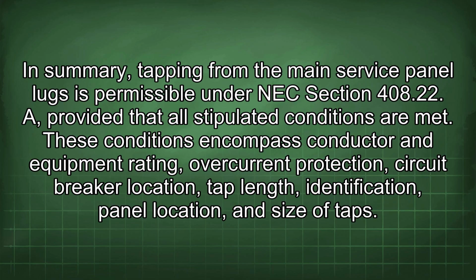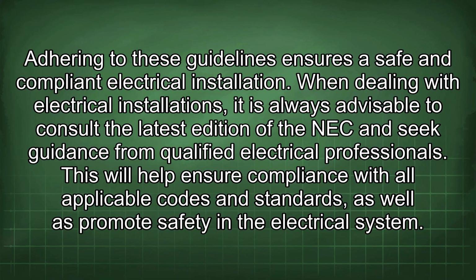In summary, tapping from the main service panel lugs is permissible under NEC Section 408.22, provided that all stipulated conditions are met. These conditions encompass conductor and equipment rating, overcurrent protection, circuit breaker location, tap length, identification, panel location, and size of taps. Adhering to these guidelines ensures a safe and compliant electrical installation.